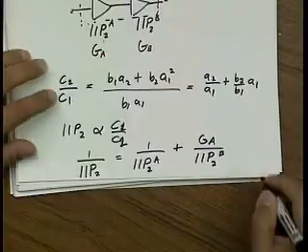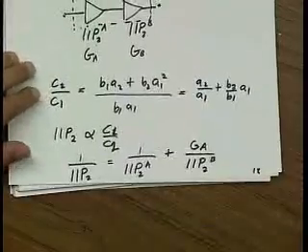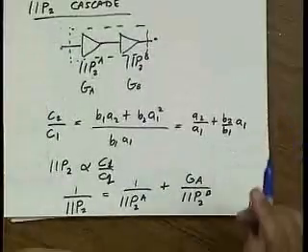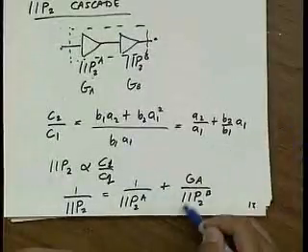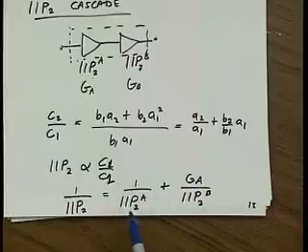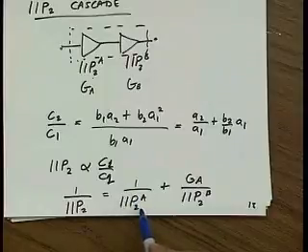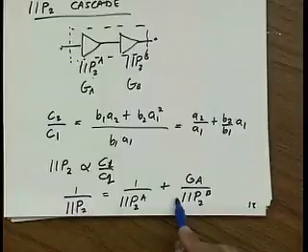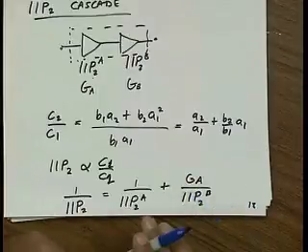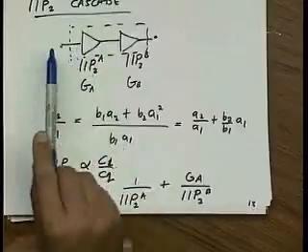Now, this is actually a very simple result because we can interpret these terms individually. Let's say that the second amplifier is linear, so this term is infinity and it goes away. That would tell me that the input IP2 of the overall amplifier is dominated by the input stage. Well, let's say this amplifier were perfect, completely linear. Then its input IP2 would be infinite, and the overall IP2 would just be the IP2 of the second amplifier, but input referred. Of course, I have to input refer it, because the signal power is here.